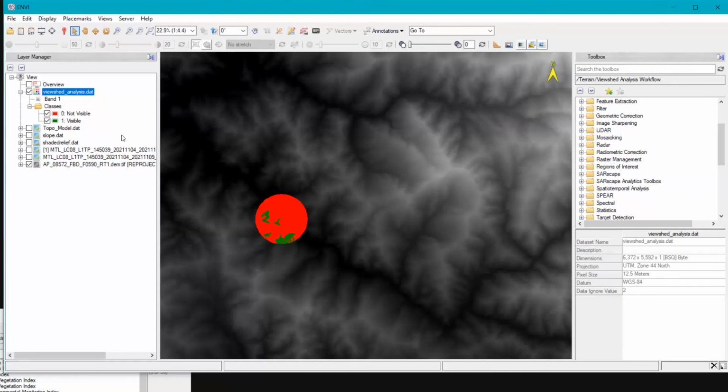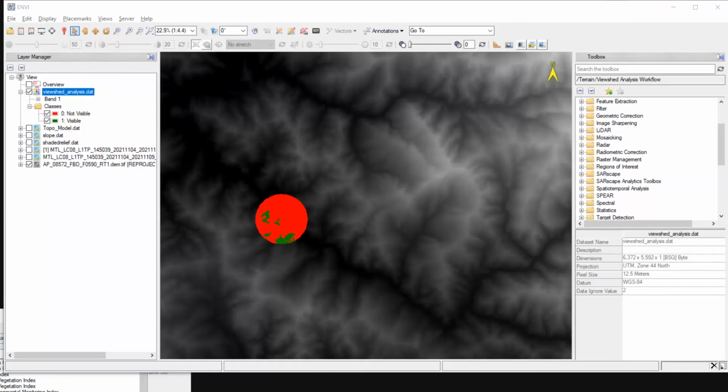Finally, for a terrain analysis, a viewshed analysis is the main purpose. A viewshed analysis can be easily done by giving a simple DEM file and a multispectral file that is completely optional. And once I've done the same, the wizard will allow me to give the default range for which I want to see the view with my viewshed, a minimum height at which I want to see, and a default spacing.